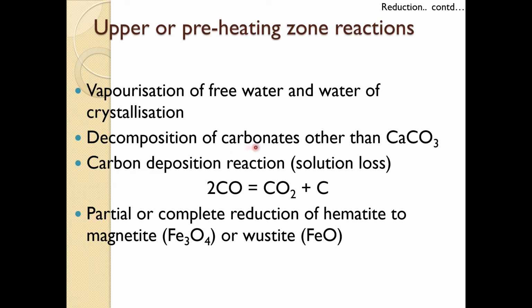Then decomposition of carbonates other than calcium carbonate occurs, because calcium carbonate decomposes at higher temperature. So mostly magnesium carbonate or manganese carbonate decomposes in this region. Even if you have a carbonate iron ore, that also decomposes in this region.